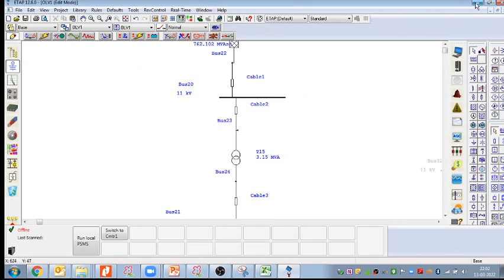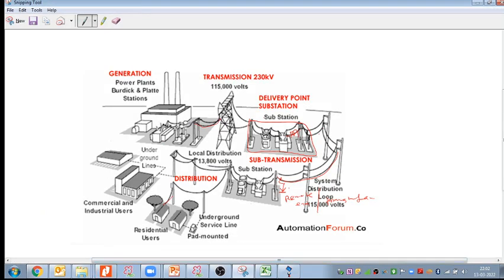Yeah, okay. Now it is very clear that this through fault is the IK max, and that is the full fault of this substation, which we can take as 63 kiloampere or whatever the maximum fault of this switchyard. And when we come to the remote-in fault, that fault we have to calculate also. That needs to be calculated, and that is already given in the tender specifications.